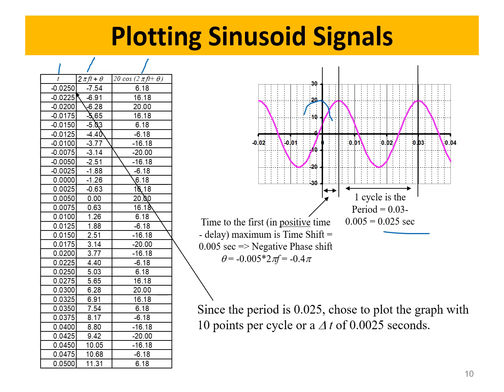But you can find the distances and measure how much phase shift you have and what your cycle is, and then you can get the period and all the information that you want from it by plotting it. So this is what we're learning: ways of how we can plot the sinusoid by learning about the period, when it repeats itself, and learning about the phase shift to know the time shift and where that thing is.